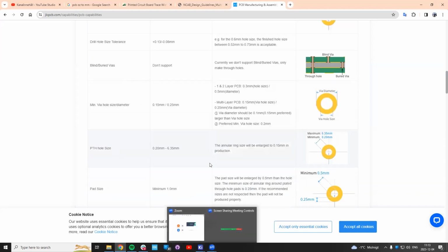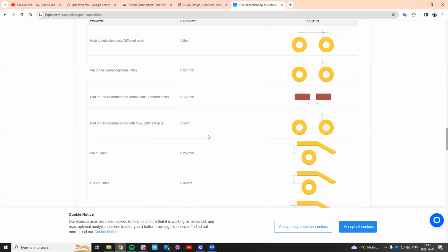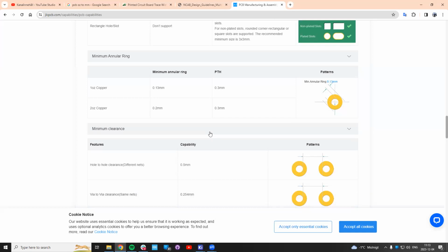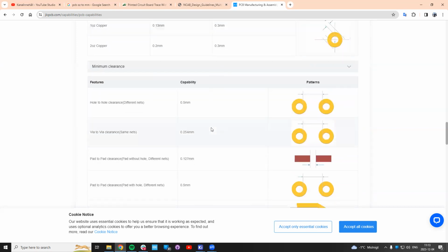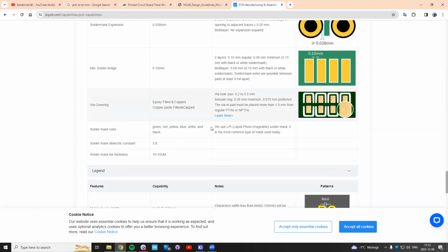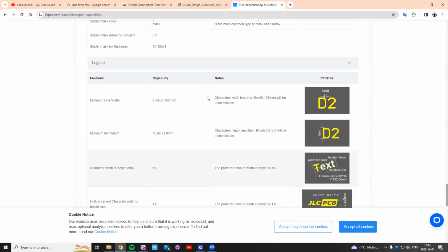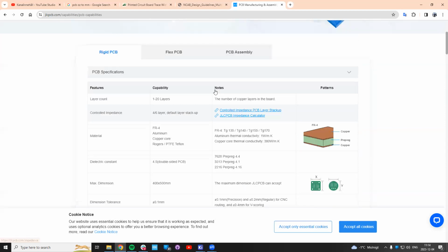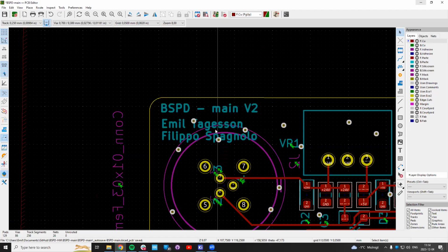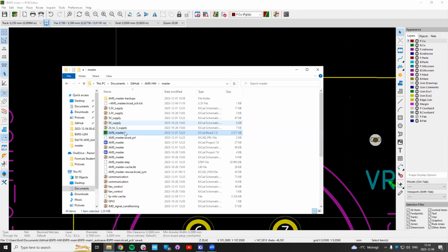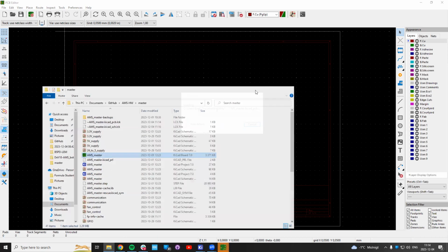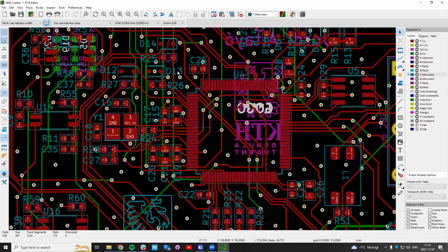I don't remember where we found this rule, but now you should go in and check that I'm not violating any other rules. So go back and check that when you're changing. Just don't change the design rules because, again, that can make the board a whole lot more expensive. This is a standard size I usually use on the vias. Or is it? Maybe I messed up here. I actually have to check in a project. Maybe I usually do 0.4. No, I usually use this via. Okay, it's okay.